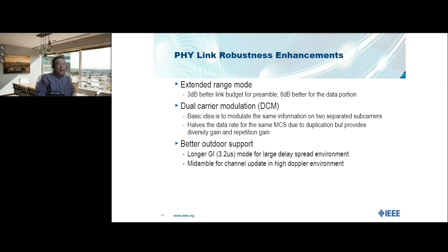11ax also has a feature called mid-amble support. If you have a high Doppler environment, outdoors with a lot of vehicles passing by, then the channel reflection from those vehicles changes a lot. In that case, 11ax provides a mid-amble, so that in the middle of the packet the receiver can use the mid-amble to refresh the channel.